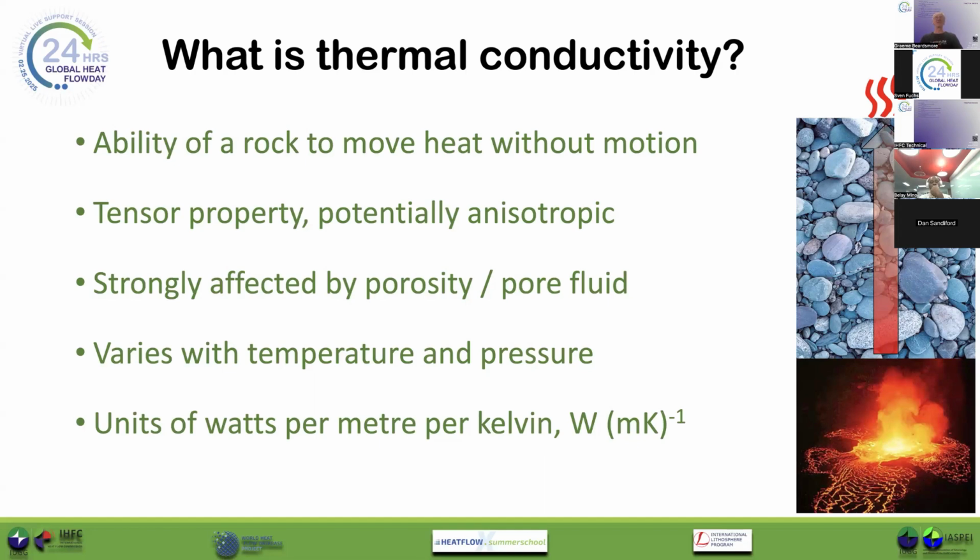I always use SI units when I'm measuring and relating thermal conductivity, and the SI units for thermal conductivity are watts per meter Kelvin. So watts per meter per Kelvin. So watts being a thermal power unit, meter being a distance, Kelvin being temperature. And so that combination of units describes how well a rock can carry heat.